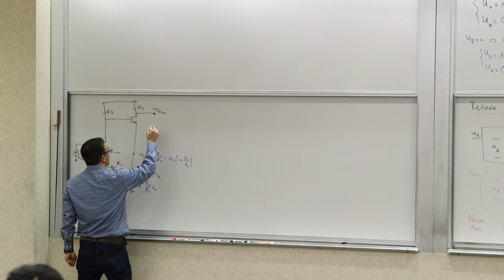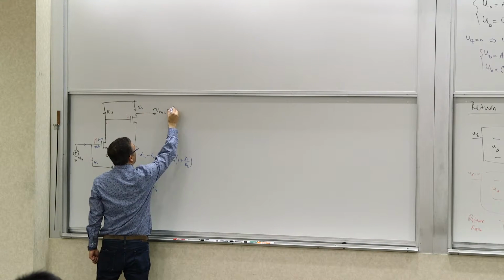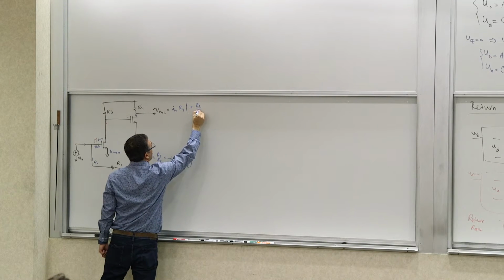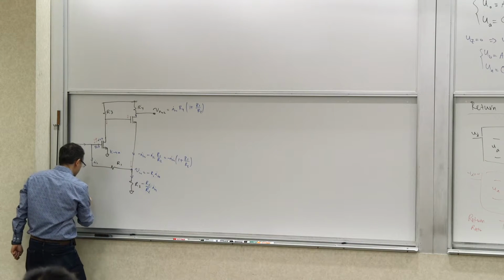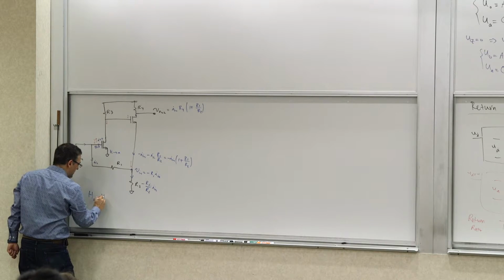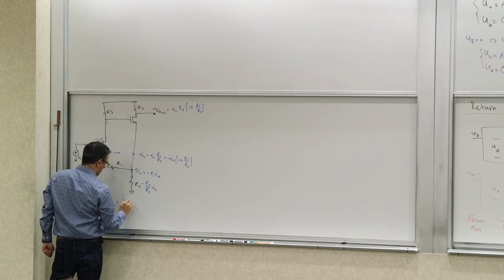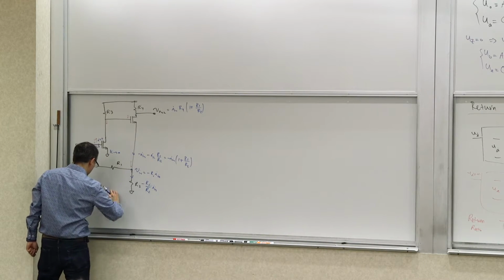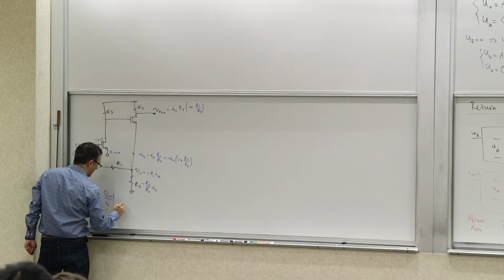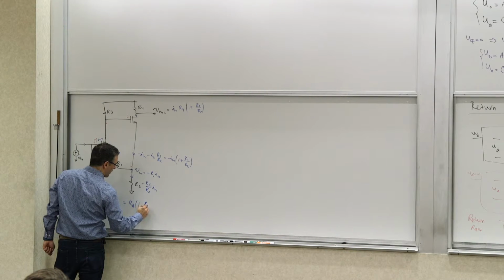So if you multiply that by negative R4, then V out is going to be essentially I in times R4 times 1 plus R1 over R2. Therefore, your H infinity, which is H when K goes to infinity, let me define it this way: V out over I in when K goes to infinity is going to be R4 times 1 plus R1 over R2.